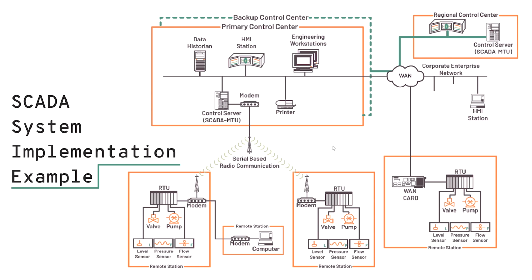So this is an example of a SCADA system implementation, and the example is useful to start understanding all the different attack vectors that an adversary can use. For example, you can jam the communications here, or these are locations that can be unmanned, so you can maybe break through the door and try to access the RTU physically there. This is a good example. You need to understand the topology of your system very well to be able to start the risk management process appropriately, and then you follow with your ICS security architecture.